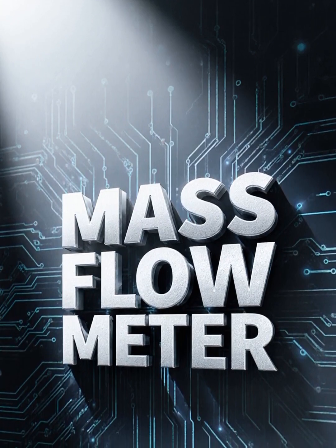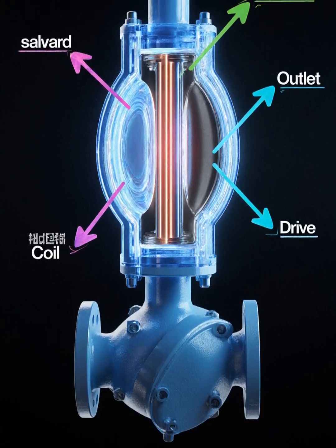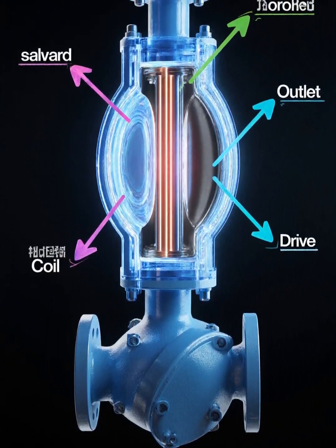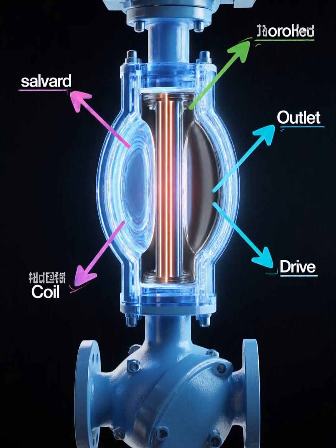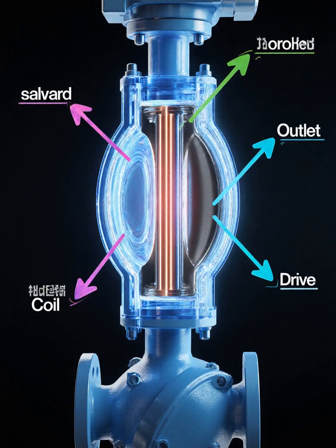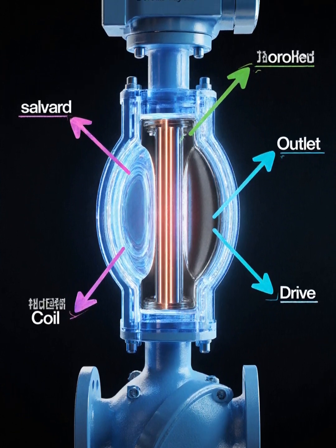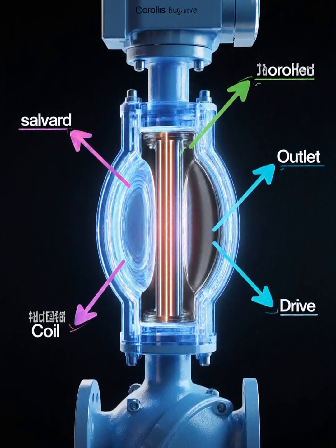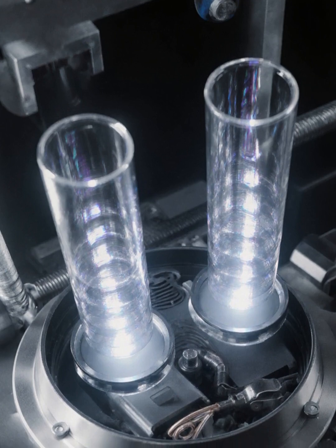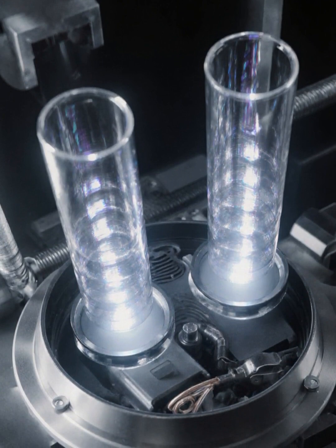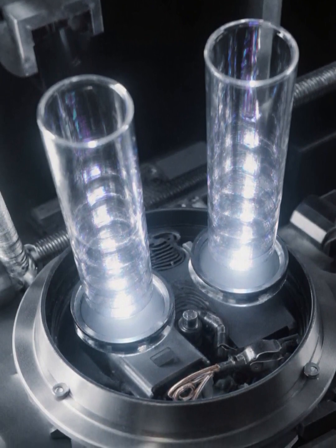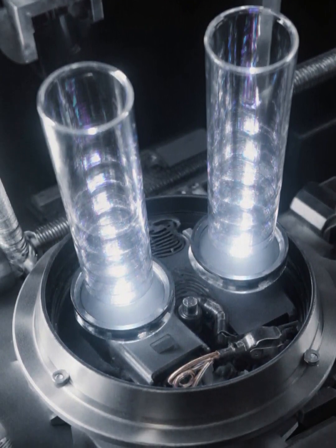Mass-type flow meter. 1. Coriolis flow meter. A Coriolis meter is based on the principles of motion mechanics. When the process fluid enters the sensor, it is split during operation. A drive coil stimulates the tubes to oscillate in opposition at the natural resonant frequency.